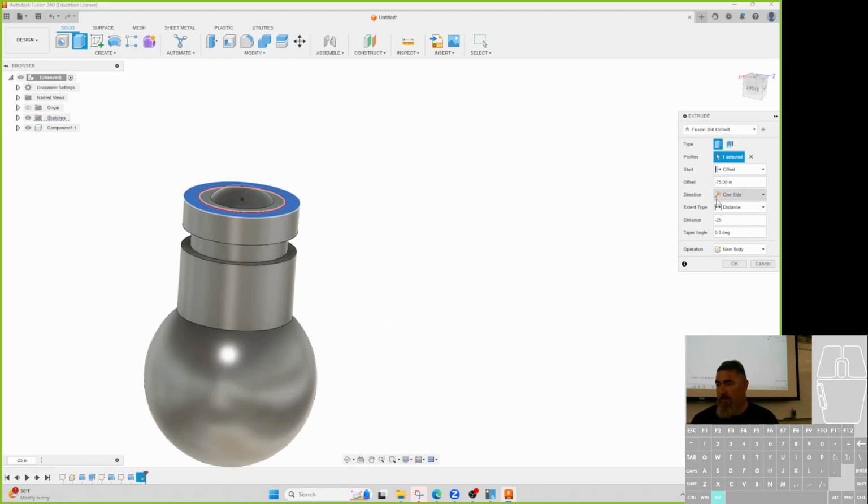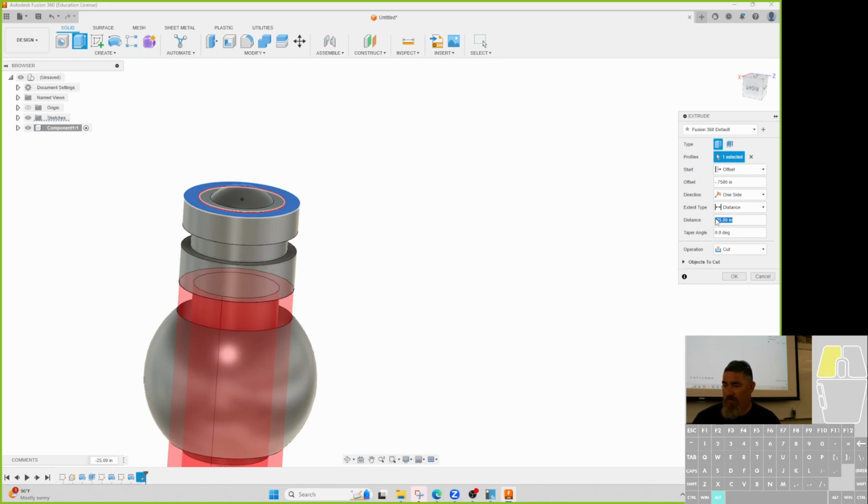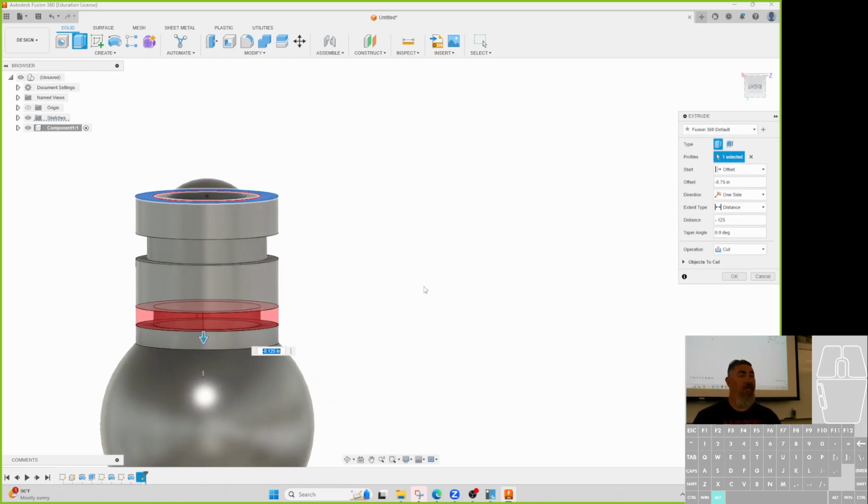Where are you? Oh, -0.75. Did I miss those? Right? So I can just tell it to go there. So instead of having to draw a rectangle, do a sketch in the middle, do an intersection, draw a rectangle, dimension the rectangle, and then revolve, I can just draw a circle and dimension it with my offsets here. Which way? Sure. Either way works. I'm starting to do it this way now, just because it kind of keeps it a little bit easier.